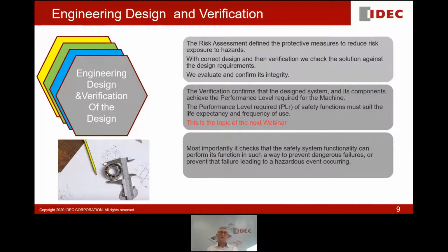And there are risk assessments against the functionality, the people putting their hands into a machine, their time of exposure. We talk about the performance level of the safety control system that's going to protect the people.